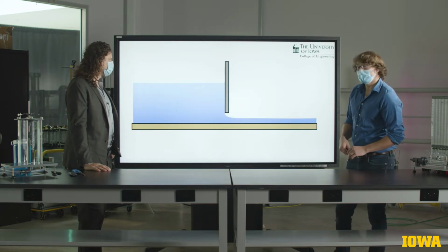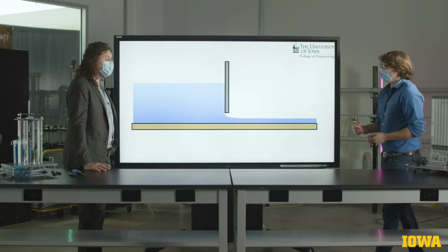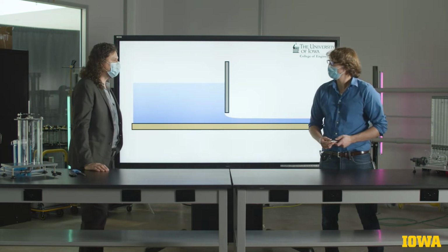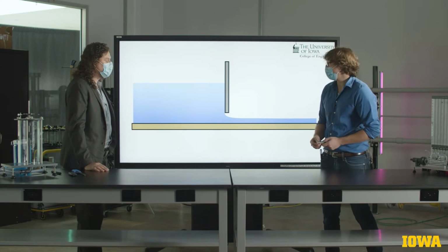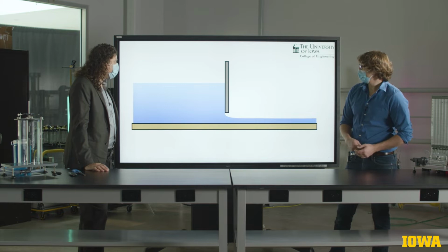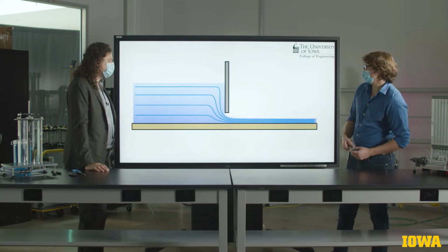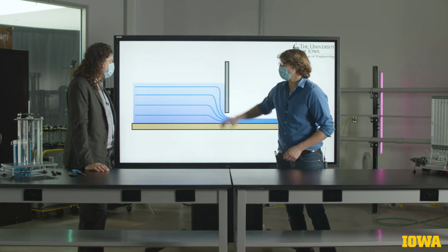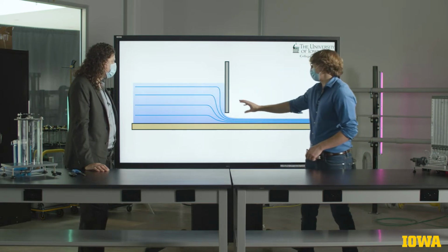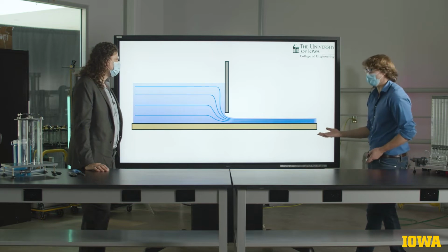However, if we lift that dam up a little bit and turn it into a gate, you could be tempted to use hydrostatics here, right? So you determine the forces that are acting using the triangle of forces. In this case, however, we have streamlines that begin pretty far apart, indicating a slow-moving fluid, squeezed together to show a fast-moving fluid as the water passes underneath the gate.